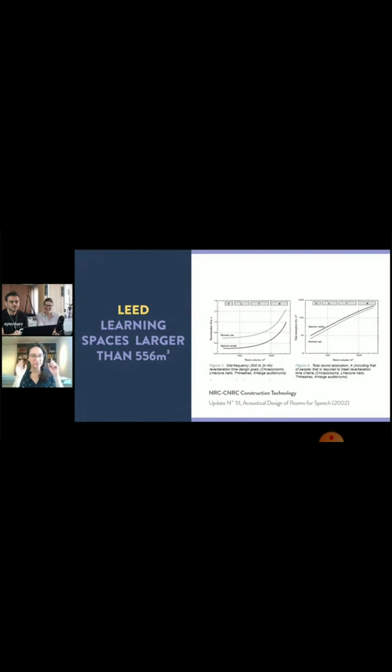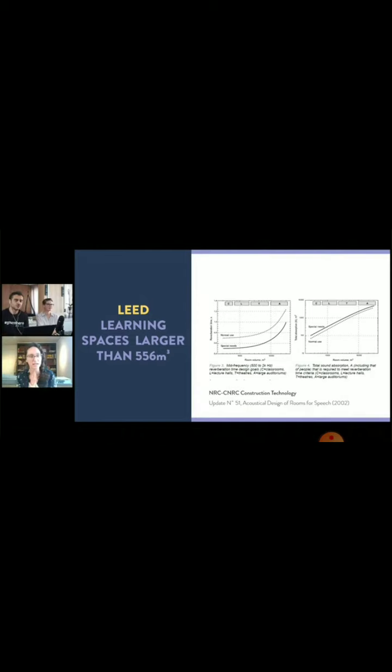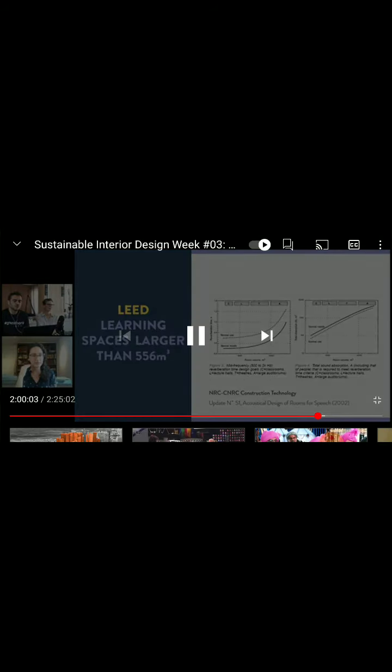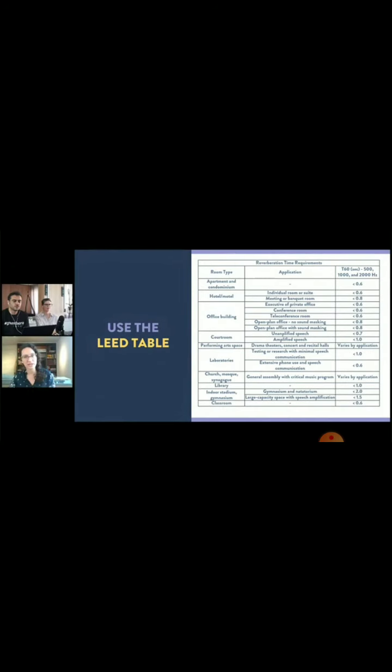Yes. And important to have in mind, reverberation time is all about the volume of the room, as Philip said, and the absorption materials. They have this relationship, and you have to have that in mind. The bigger the room, the higher the volume, the higher the reverberation time. This is why in an apartment I have to have a reverberation time lower than 0.6 seconds, and in an indoor stadium, for example, I can have from 1.5 to 2 seconds, which is the time that sound